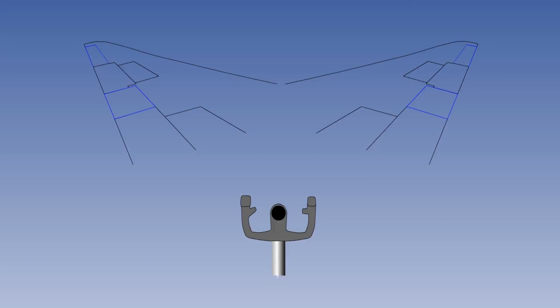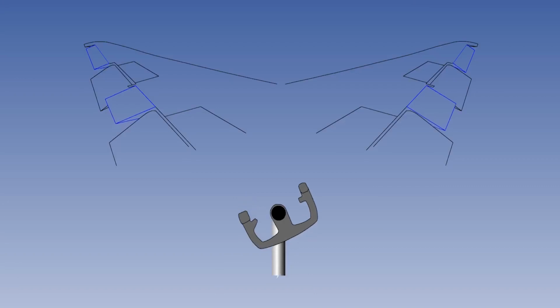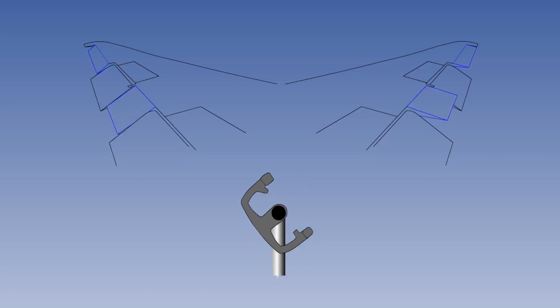When the trailing edge flaps move down, the flaperons also go down. Now the whole wing area has its camber increased, thus maximising the effect of the flaps to increase CL max. But what about lateral control? Think of the flaperon position with the flaps down as a new neutral datum. When a roll input is made, the flaperons move up and down from this new neutral datum and still provide a change in lift on both halves of the wing for roll control.